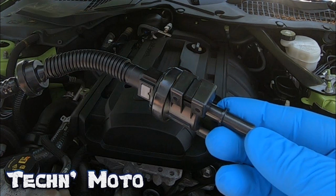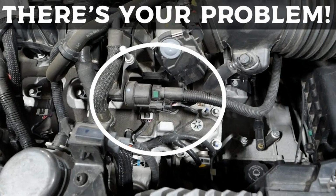But if you're confident in your knowledge of EVAP systems, here's a list of all the potential causes of a P0496 code: faulty EVAP or fuel pressure sensor; EVAP hose leak, a common problem on Hyundai vehicles; blocked EVAP canister, clogged vapor canister, damaged canister; drain valve; faulty solenoid, purge valve; faulty purge flow sensor, especially on Kia and Mazda vehicles; weak electrical connection or short circuit, common on Isuzu and Hyundai vehicles.